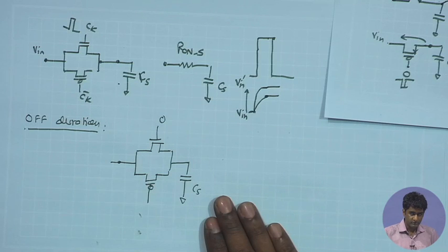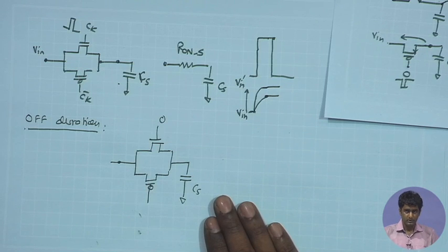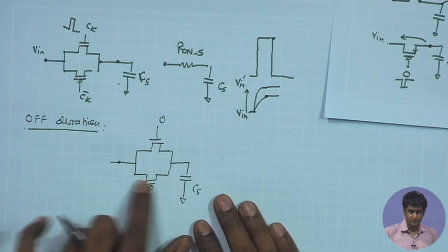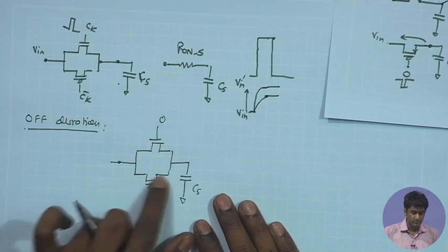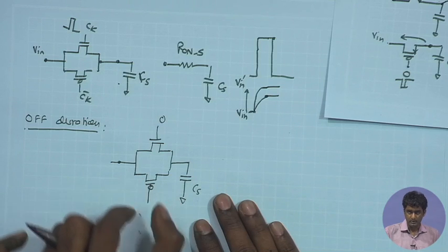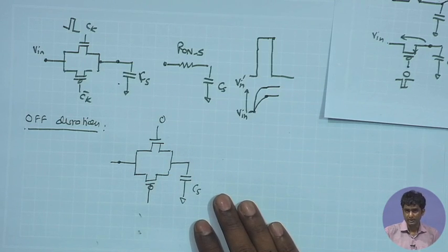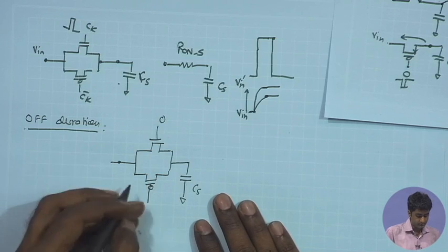However, the reverse bias junction leakage can be pretty significant, and that is something which also increases proportionally with the W of the transistor. So, the subthreshold leakage for example can be reduced if we are having longer channel length, that imparts a relatively longer channel behavior to the MOSFET, and that can reduce the subthreshold leakage current. But if we are looking at the junction leakage for example,